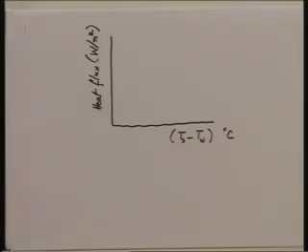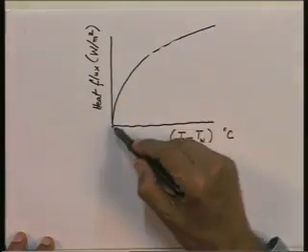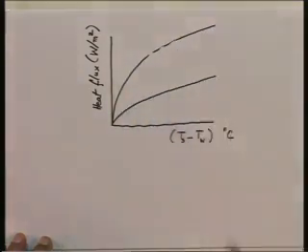Typically, if you collect experimental data, in one case for film condensation occurring on the surface, in the other case for drop condensation, and through the experimental data you draw some curves. Typically, in dropwise condensation you might get a curve something like this. In film condensation you might get a curve something like this.